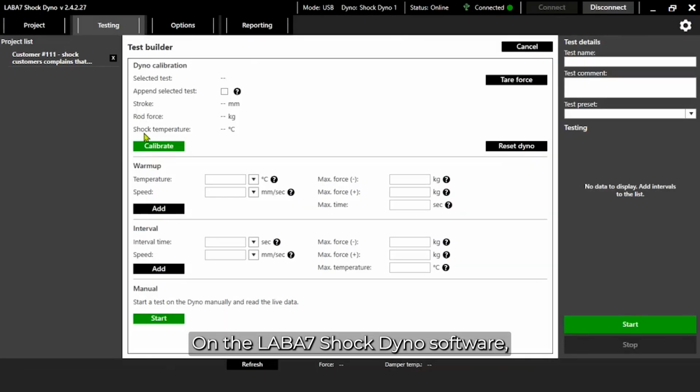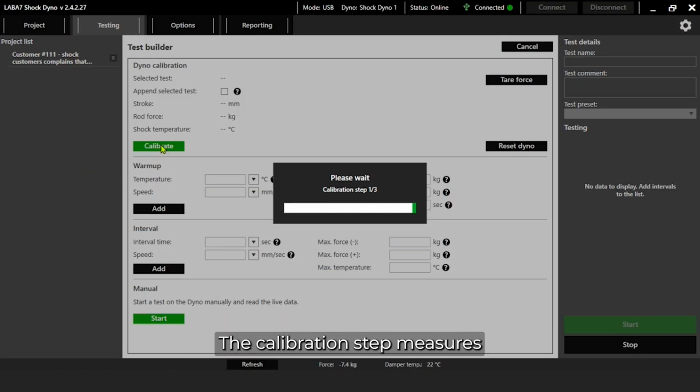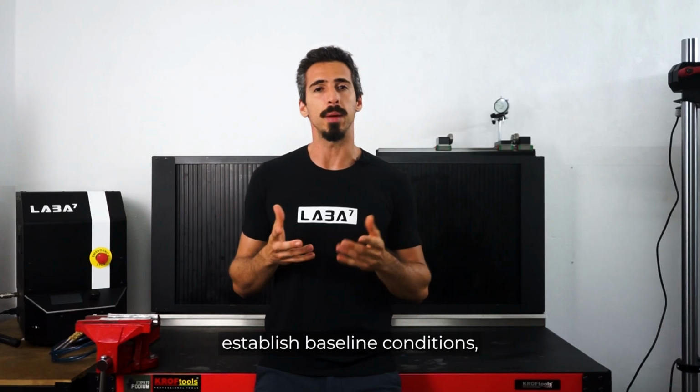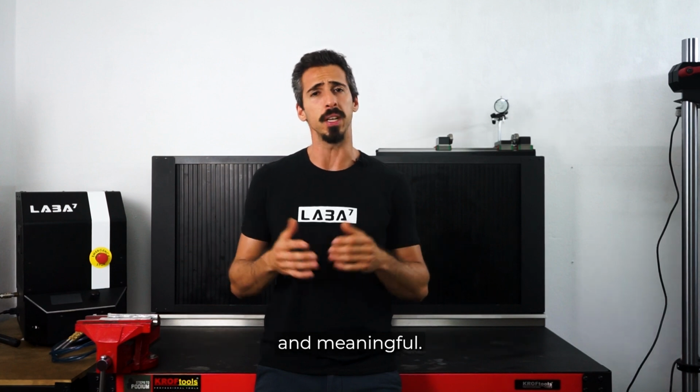On the Laba 7 shock dyno software, go to the Testing tab and then click Calibrate. The calibration step measures your current stroke length and preload force. We recommend calibrating your dyno before every test. This process helps the software establish baseline conditions, which ensures that all test data is consistent and meaningful.